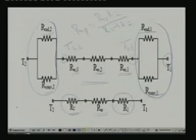So this is the simplified resistance network for the given problem. Now, what is the total resistance? As you know, R total is nothing but sigma R. So here it is simply equal to R1 plus R wall plus R2. We can find the individual resistances, because we have already given the expressions for radiative resistance, convective resistance, conductive resistance, etc. If you have the property data and other data, you can find the individual resistances and the total resistance. Once you know the total resistance, you can find the total heat transfer rate, because heat transfer rate is nothing but T1 minus T2 divided by the total resistance. So you can see the usefulness of the network analogy. Complicated problems can be easily broken down into simple problems.